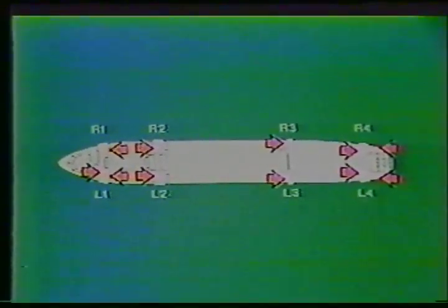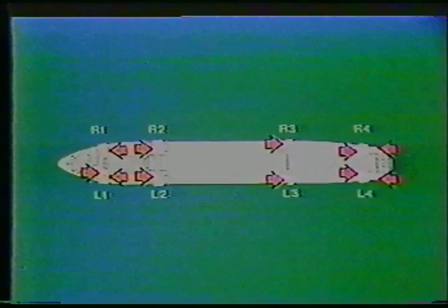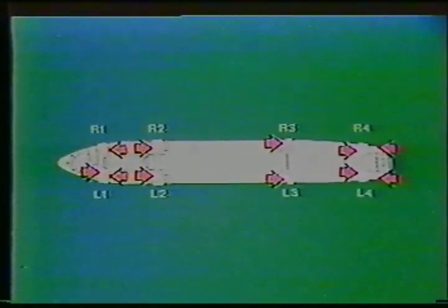For greater access, emergency equipment on the A300 is located relatively close to each of these jump seats. At L1A, there is a lighting control panel above the jump seat. The emergency light switch is located on this panel in the upper right-hand corner.